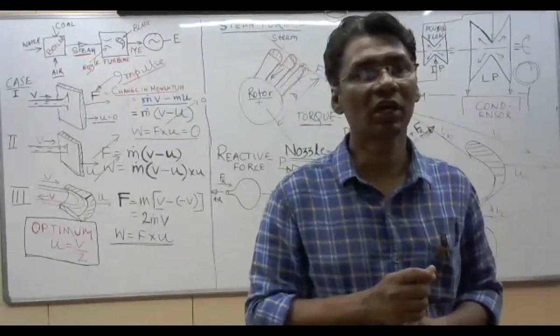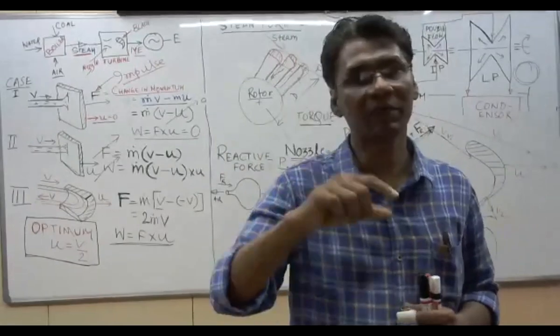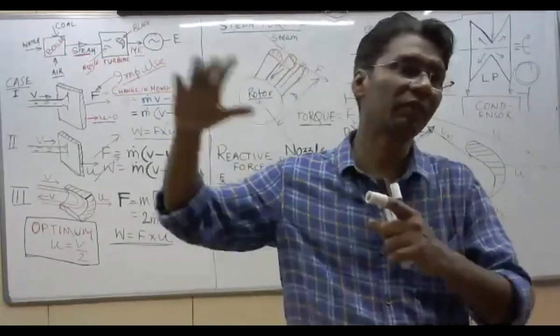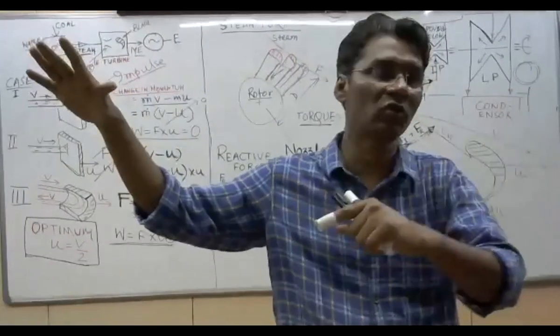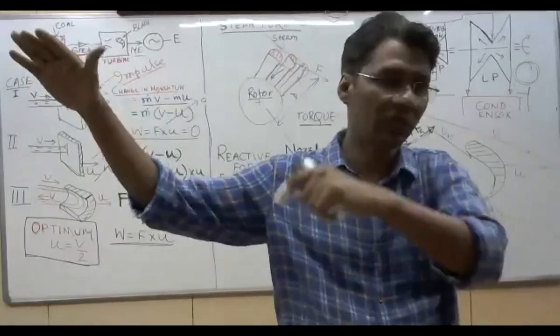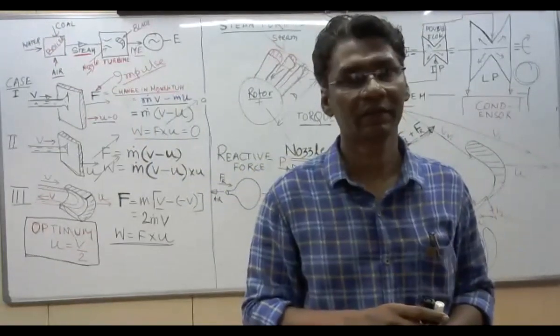The control valve controls the amount of steam going into the steam turbine by oil pressure, depending upon the load on the generator. If the load is higher, we supply more steam. If the load is lower, we reduce the steam by the control valve. Next.